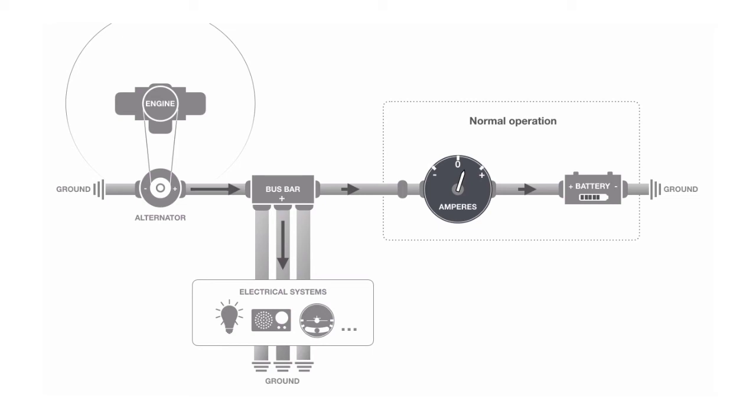When the aircraft's electrical systems demand more current, the battery contributes to the supply. Consequently, the ammeter needle moves slightly to the left of zero as the battery discharges. Again, since the battery has a finite charge, it will only supply the extra current for a limited time. To fix this problem, switch off unnecessary electrical equipment to reduce the load until the center zero ammeter indicates a charge.